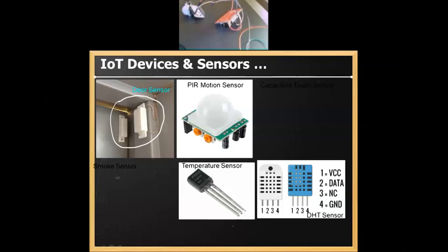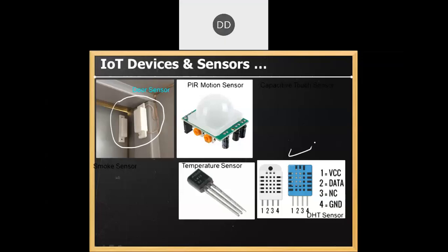This is the device which I have already shown to you. Yes, please. Sir, for door locking, we have to use a capacitive sensor, sir. You can use either a capacitive sensor or, like what I have shown here, a magnetic sensor. But you can always use a capacitive sensor or simply a switch also. Whenever you shut the door, the contacts will come together. So any kind of sensor you can use there.